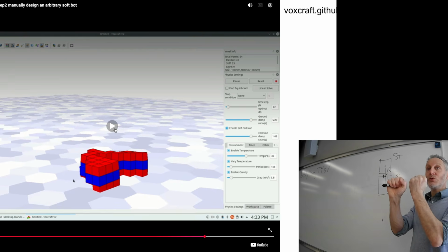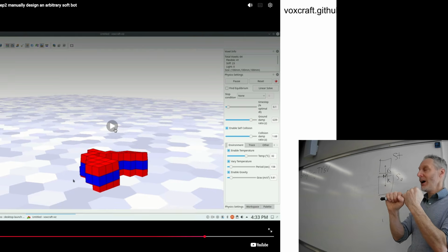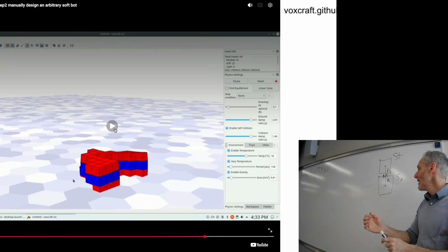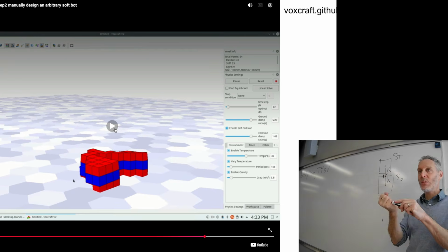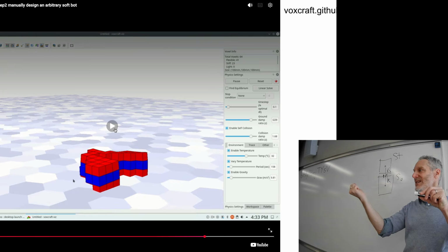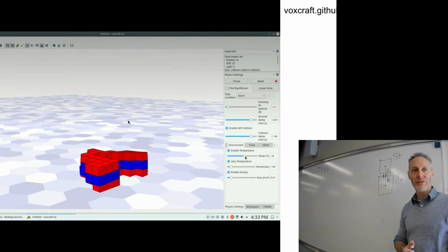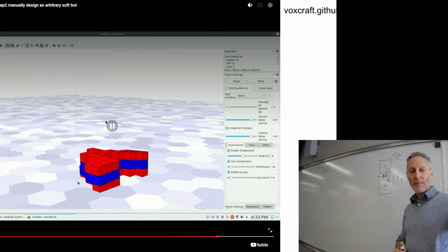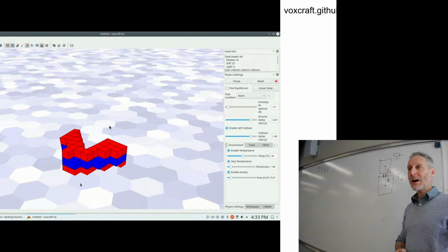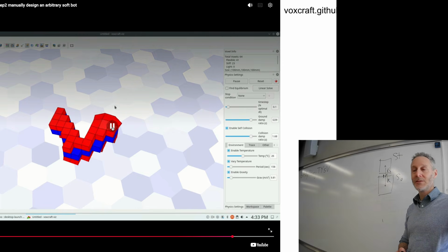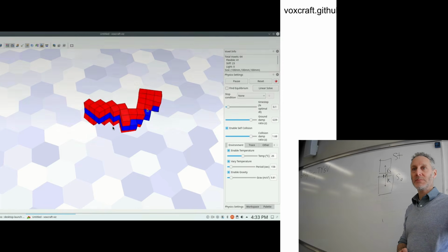The motors could also do the other 5 forces that we talked about. In this case, the motors only apply forces pushing those 2 beams apart and trying to pull them together. If we attach a central pattern generator to that motor, it's going to rhythmically extend and compress every half beam, which it's doing in this simulation, and this is the result you get. Now we can start to talk about a robot. This robot doesn't go anywhere. Why not? Unless somebody pulls on it.